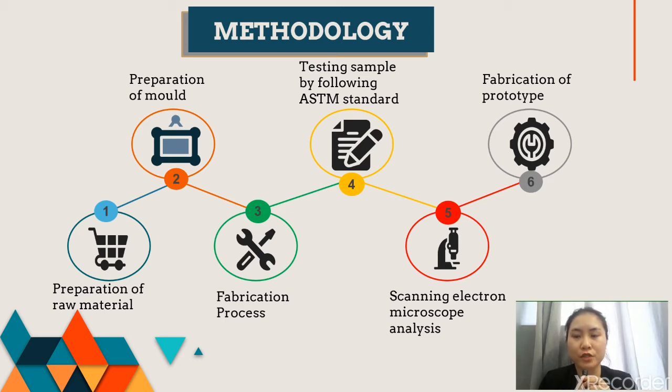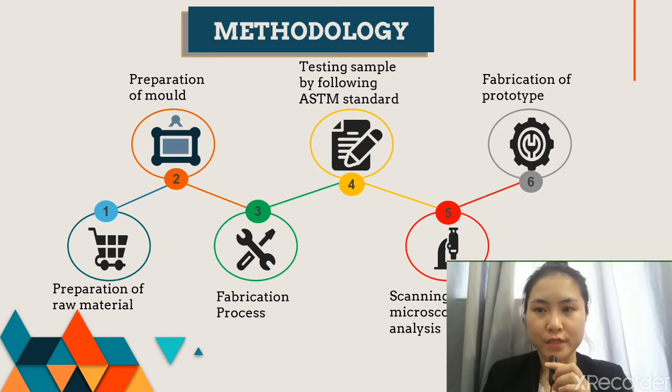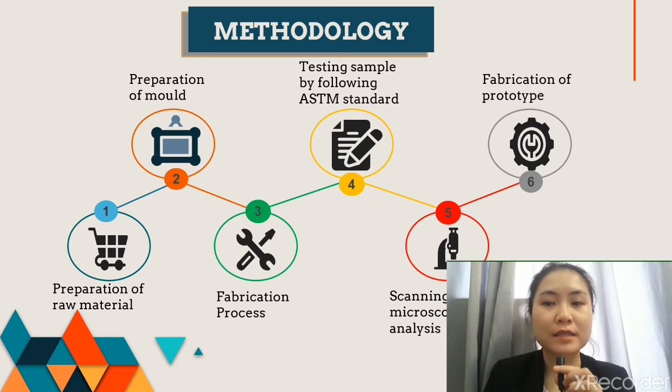According to the product features, it is 100 times thicker than the original coating and has a strong heat insulation effect, as it can withstand up to 1000 degrees Celsius. For the surface of metal, it resists up to 120 minutes and wood resists up to 90 minutes. Before applying it, the surface of the sample must be completely clean and dry. Moreover, the surface temperature must be at least 3 degrees Celsius above the dew point to prevent condensation.